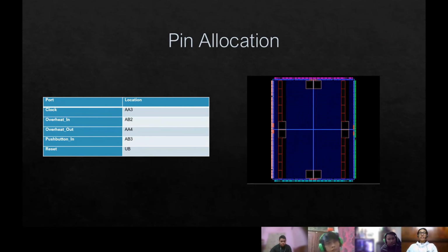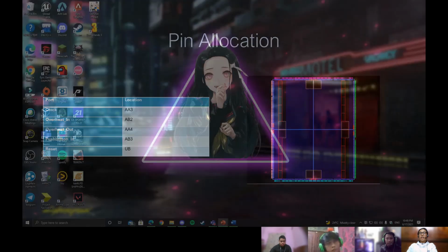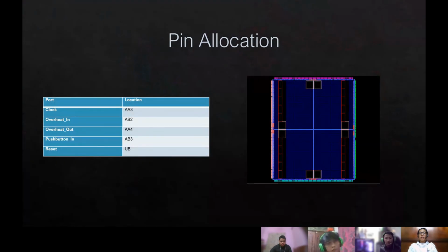Pin allocation is the process that needs to be of concern should the programmer want to test their design onto the evaluation development board. This can be found at implementation or user constraints or floor plan area. Different boards has its own user constraint file, or we call it UCF, to map the inputs to outputs. The programmer needs to select the pin.